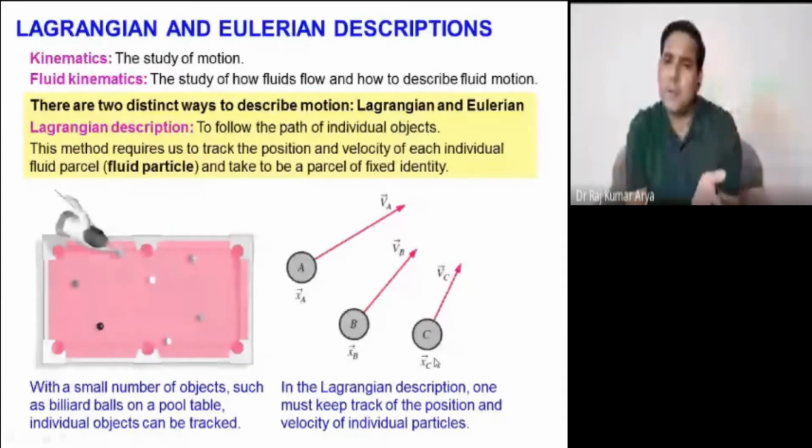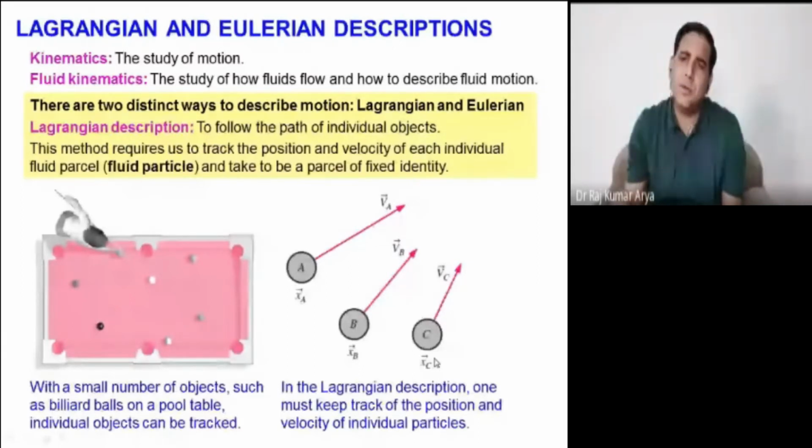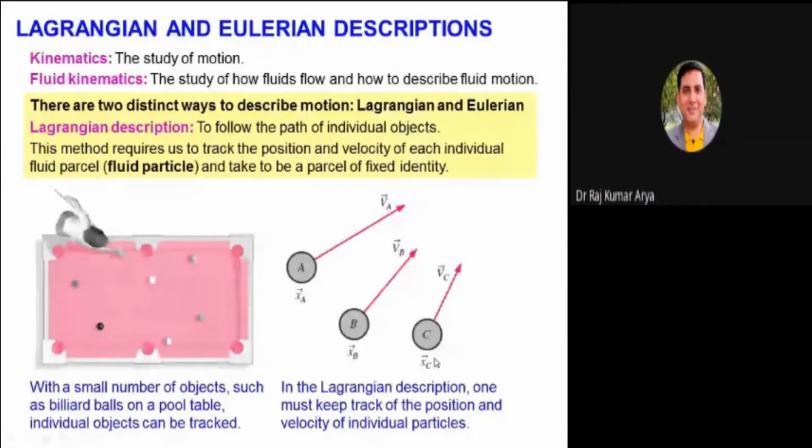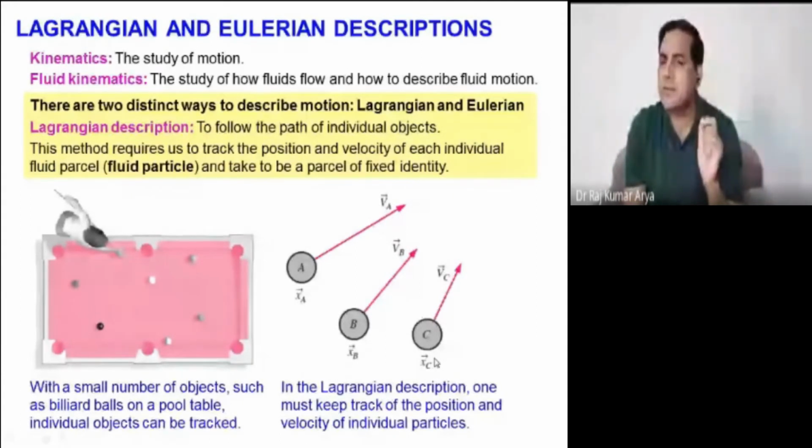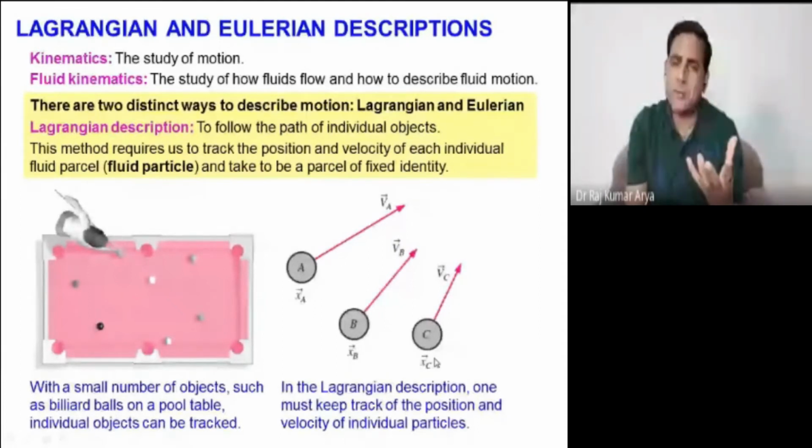You can also do the force balance, your momentum change and everything. Then for each you can write one for energy balance. Energy also needs to be calculated. So for each particle you can write your mass balance, your force balance, and your energy balance. These are three main balances. So for each particle you can write three, and now you have three particles, so you have nine equations.